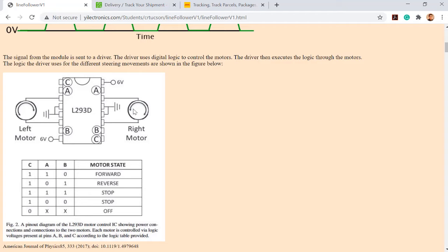Whenever we talk about a heavy load, it's because that component is drawing a lot of current from the source. A small resistor will be a heavy load for the circuit because, using Ohm's law, voltage over resistance will give you a high current.